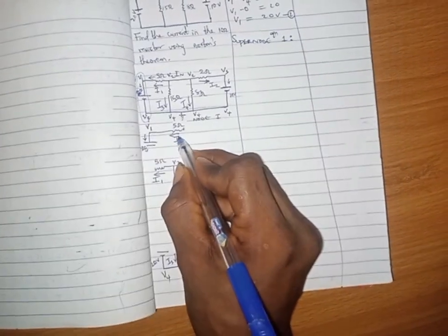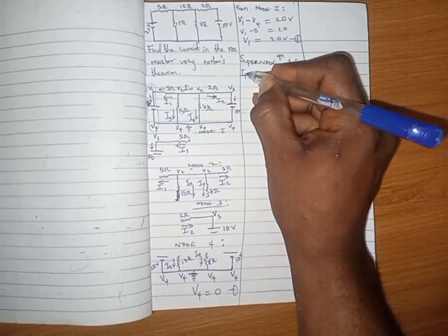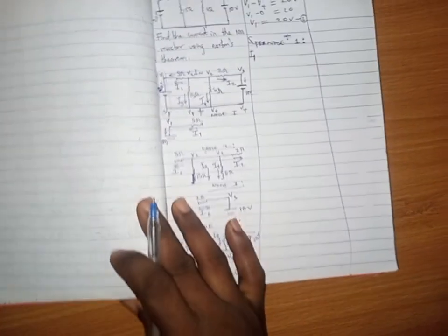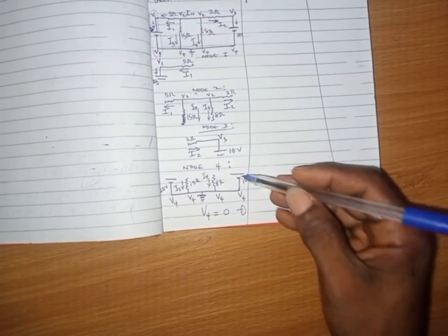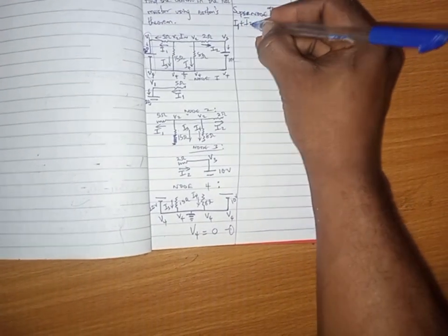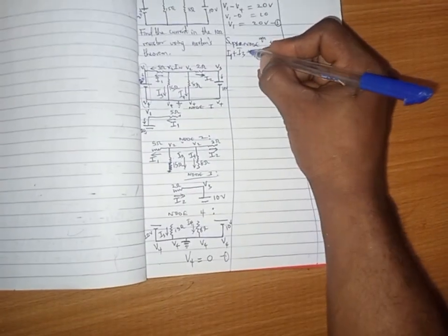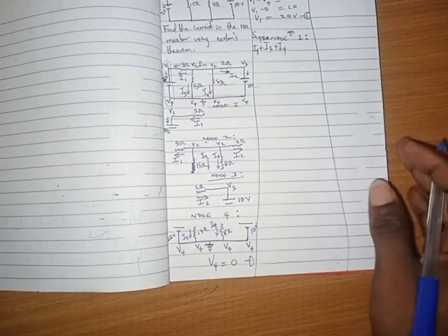So to get that, we'll come to this place. We'll see that I1 is entering the upper voltage, which is I1. Anything entering is positive, anything leaving is negative. I1 is entering, positive. Now, lower voltage is V4. What is entering V4? Entering V4 is I3 and I4. Any other currents? So just this. So let's go to the main circuit and check if we are correct.